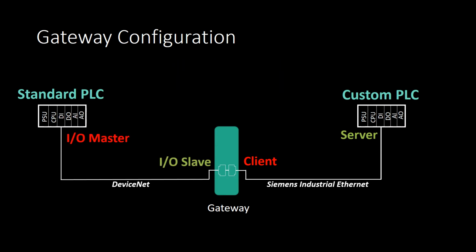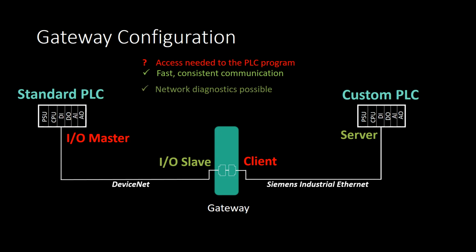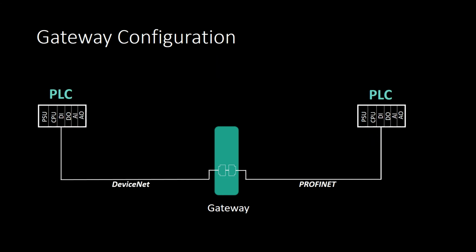The best solution is to use dedicated I/O messaging. This sets a dedicated update rate between the PLC and the gateway, which gives fast and consistent communications. The PLC program can also use tags to identify gateway problems or other network issues. I/O communications are the fastest and most consistent connections and should be used whenever high speeds are required and if the protocols used support it.